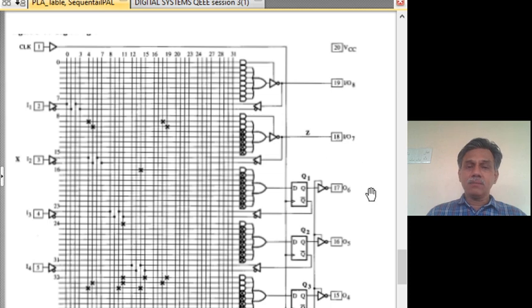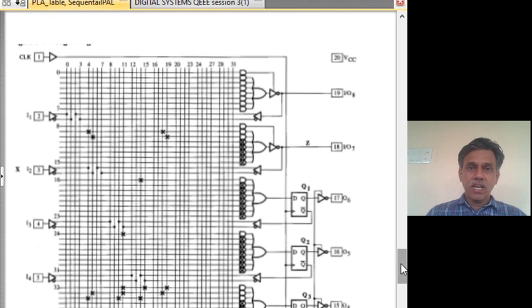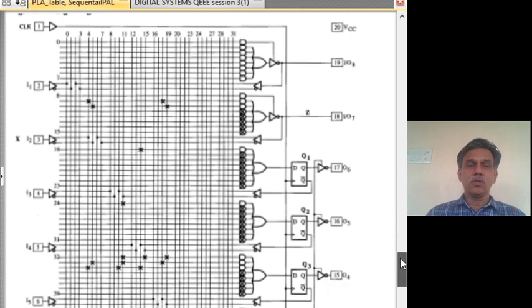Apart from that, we can use this in many ways in which you can configure it. In fact, instead of using it as an output, we can also use it as an input, just like this. So instead of 8 inputs, we can also have in addition a maximum of 8 plus 4, 12 inputs. Or if you want 4 outputs, we have to restrict to 8 inputs, and so on. So there are many ways in which you can use this one.